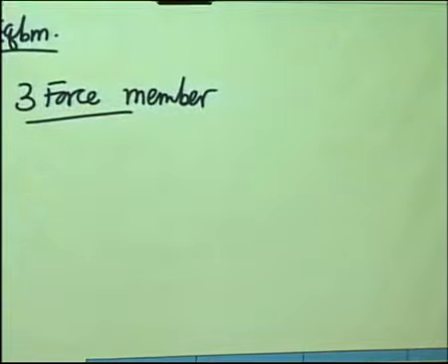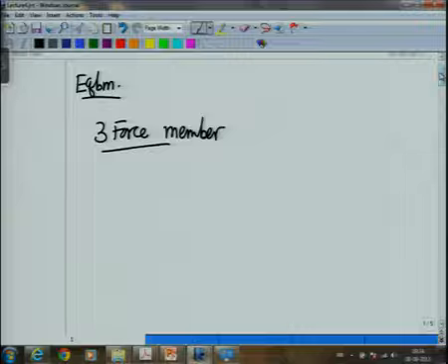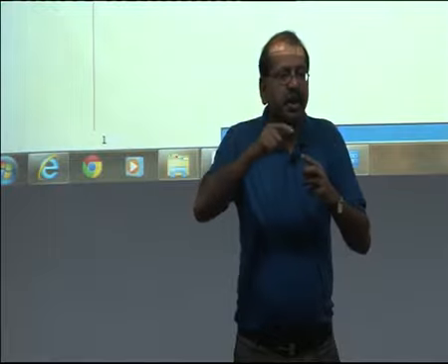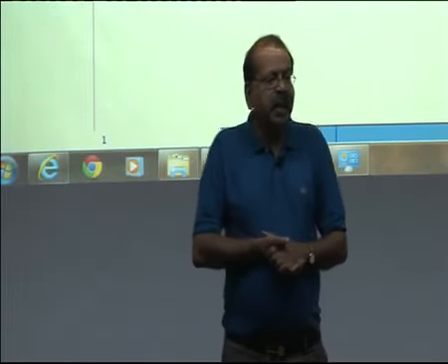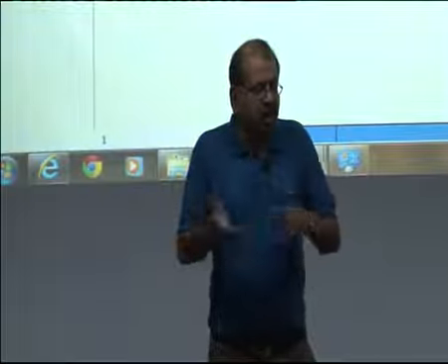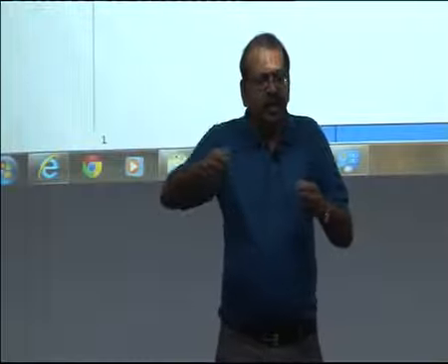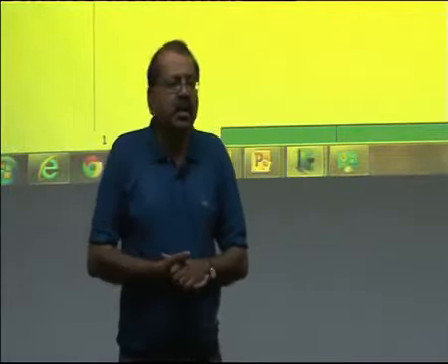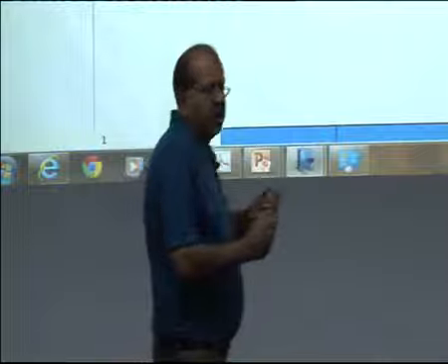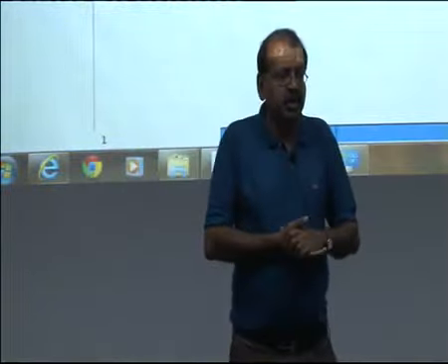Now, the reason I didn't do this is because often, for example, in a two force member, we do realize that if there is an element on which only two forces are acting, then just that knowledge helps us to make the problem simple without directly applying the equations of equilibrium. The conclusions from the equations of equilibrium, that the forces will be equal and opposite and will act along the same line, are useful enough to be used.